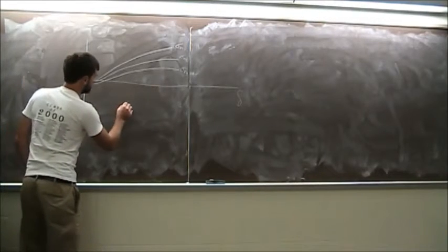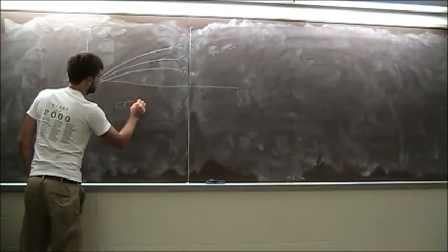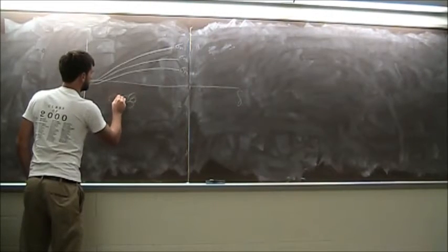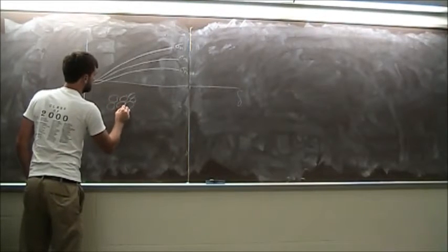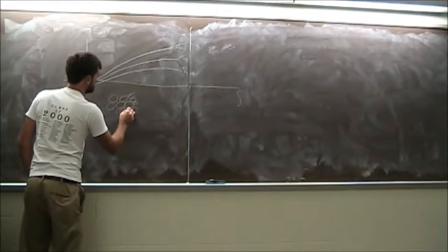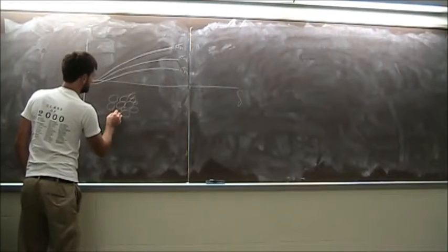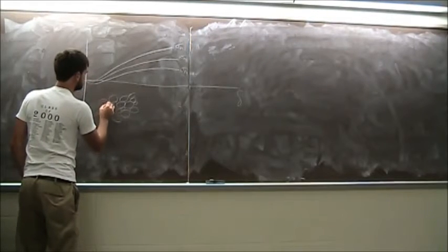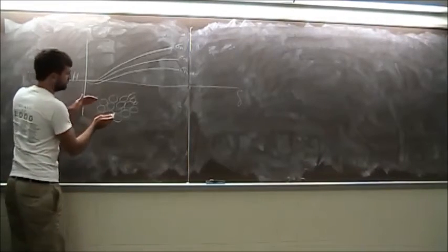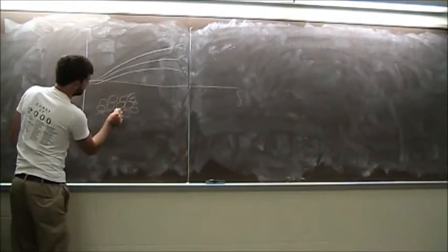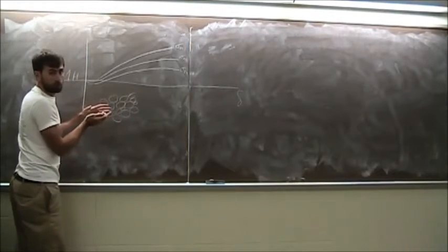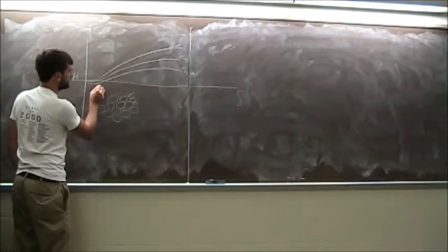And what you're seeing here is, if you have particles being sheared, your particles are not in their densest configuration to begin the test. So initially, when you move these couple particles, they might get slightly denser, and then your volume is going to shrink. So that's what you're seeing here.